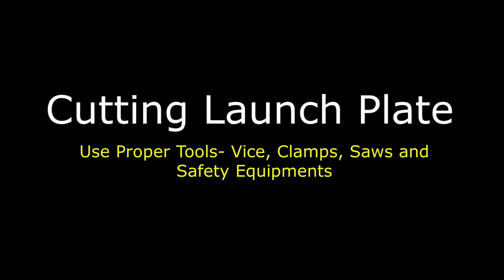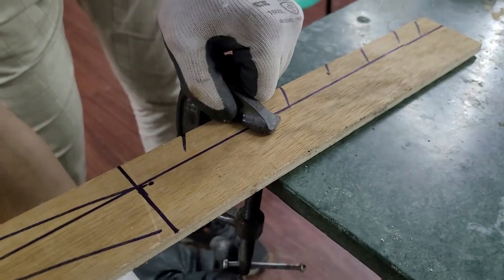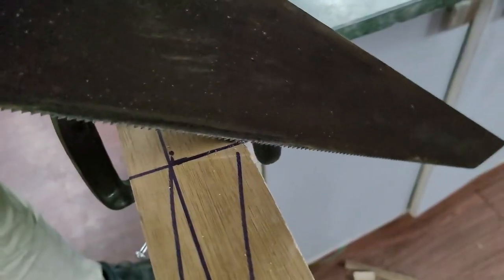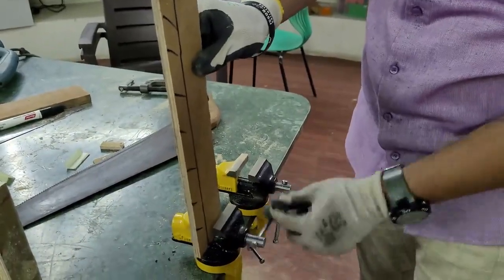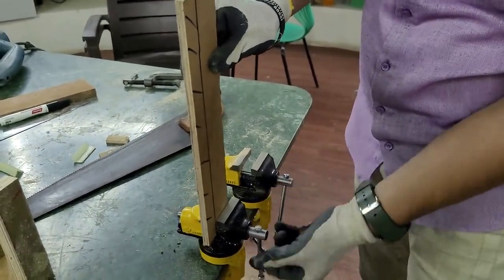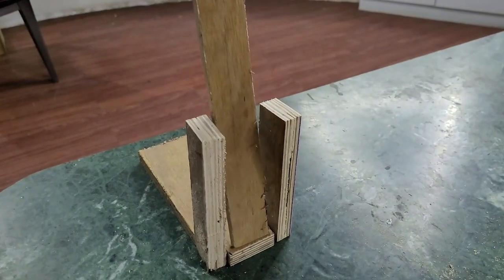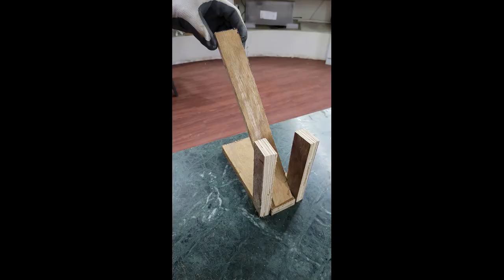Now cut the launch plate. Again, use proper tools, clamps, saws and safety equipment. Now the launch plate, again clamp the cutting edge very close to the table. Now for cutting along the vertical length, turn the job, clamp it vertically into the vise. And since it has more overhang, cut it easily and slowly. Check all the parts together when they are cut, whether they are fitting appropriately, and have enough gap between the two plates. This is how it will look when all the parts are cut.